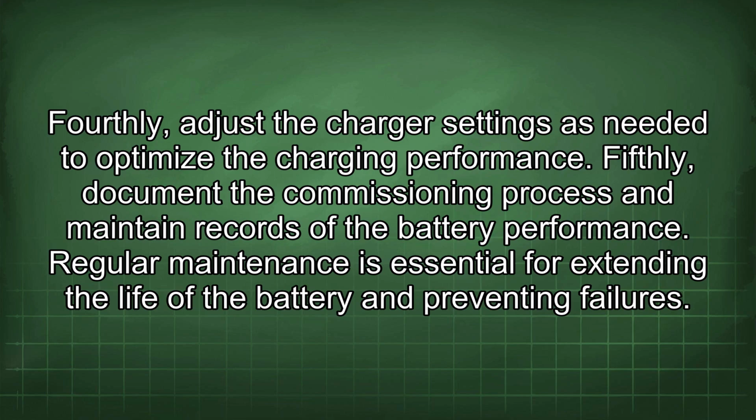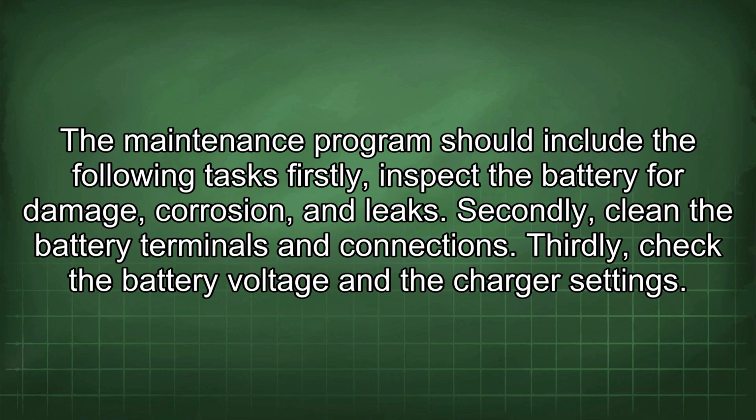Regular maintenance is essential for extending the life of the battery and preventing failures. The maintenance program should include the following tasks. Firstly, inspect the battery for damage, corrosion, and leaks. Secondly, clean the battery terminals and connections. Thirdly, check the battery voltage and the charger settings.